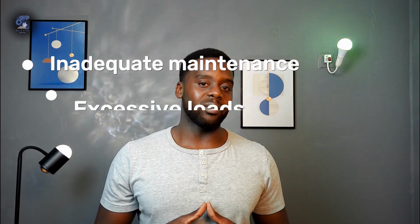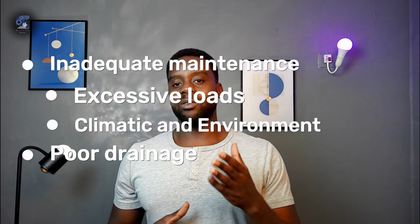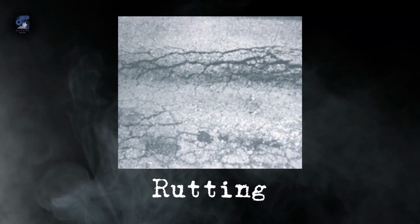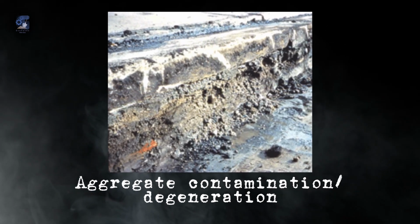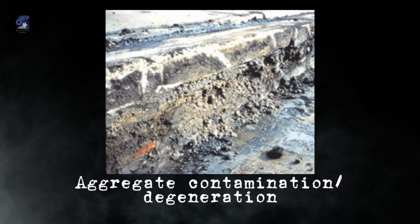The causes of these failure conditions may be inadequate maintenance, excessive loads, climatic and environmental conditions, poor drainage leading to poor subgrade conditions, and the disintegration of the component materials. You can see excessive rutting, where the subgrade exhibits wheelpath depressions due to loading, aggregate contamination or degeneration, which is the presence of unwanted materials in the base and the subbase, or the physiochemical breakdown of the aggregate over time.